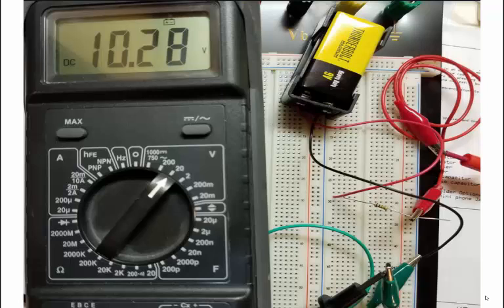In this lab, we connect a digital multimeter to a voltage source in a series circuit with a large resistor. In this case, I've chosen a 1 megohm resistor, and I'm just using a 9-volt battery as the voltage source. And current will flow from the battery through this red lead to the breadboard, through the resistor, through this alligator clip that's connected to my meter. Current will flow through the meter, back out through this green alligator clip, back to the supply, the battery.